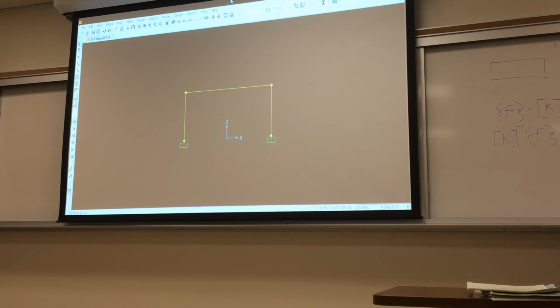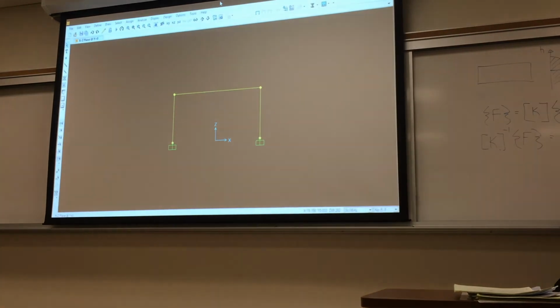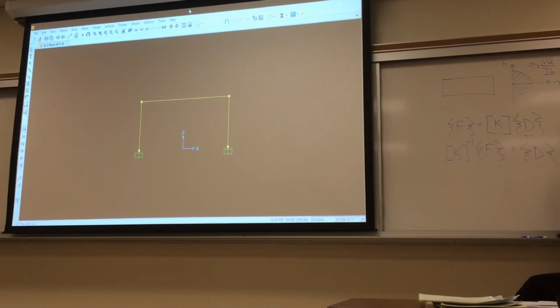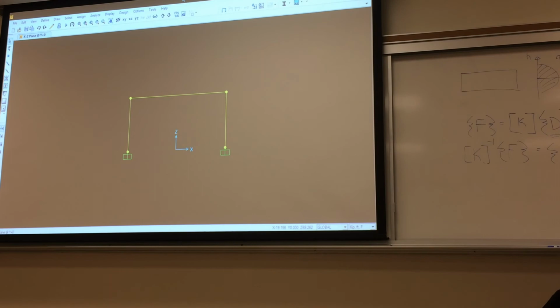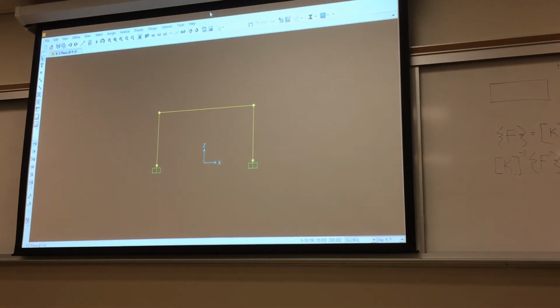You have some way to compare your hand calc of your dead load moments and shears with your computer analysis. What are we also interested in doing? We're interested in pushing this frame over and seeing how plastic hinges and such develop. So before I start developing the hinges stuff, I'll just show you how to walk through this kind of sequentially and check your work along the way.